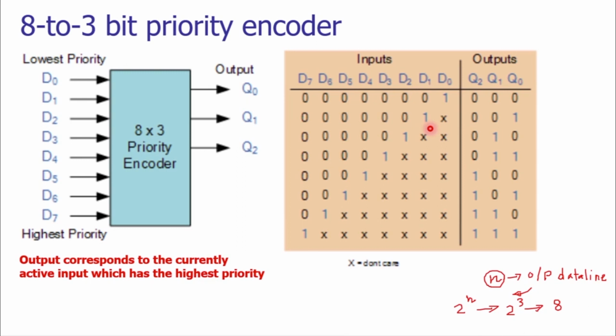The comparator is giving high level input value at D1, that is a positive. There is a comparator at D0 as well, but we are ignoring the input value at D0. That means we are giving priority to D1, although we may have certain high input at D0.